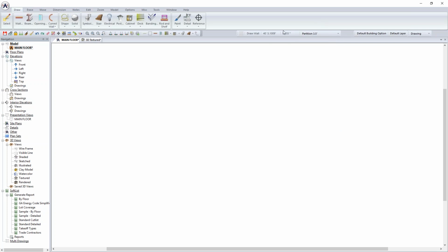It would also give me information such as the tape measure. And you're going to see in just a couple of minutes when I begin sketching, I'm going to refer to a phrase, sketch and edit. And in a lot of cases, this is something that you need to learn within the software realm of SoftPlan, which is we want you to sketch out the approximate wall length, because we're going to allow you to efficiently edit the length of that wall type at a later time. So what we're trying not to do is block you in on your design. We want you to freeform it, and so on.